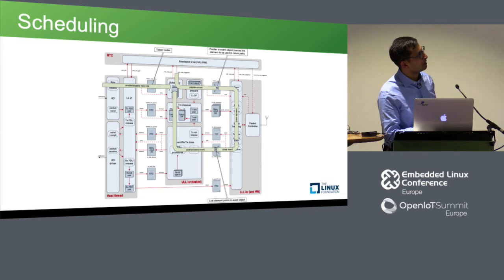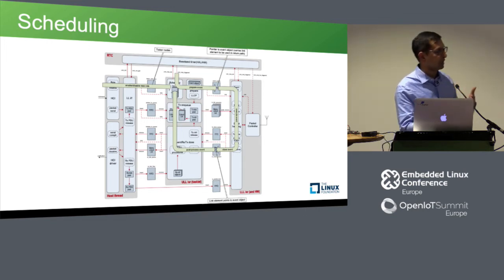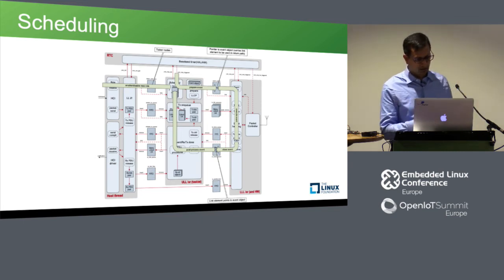The upper link layer would then set up the counter compare registers. When the compare triggers, the requests are then placed into a pipeline, because you could have overlapping schedules. They will then be placed in a pipeline and then they would schedule the preparation for the radio event in the lower link layer. Once the radio event is finished, which is basically the packet transmission and reception, there would be a message sent back to the upper link layer saying that that particular event is finished. The upper link layer would then look into the pipeline to see if any other overlapping events are there, back to back or very close, then it's going to run the lower link layer again.